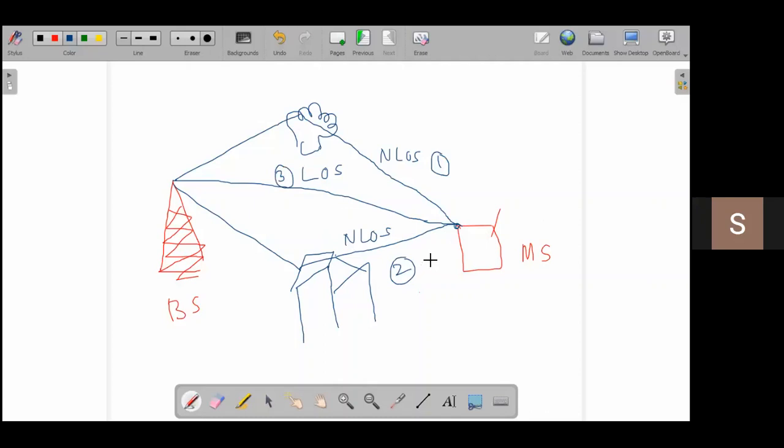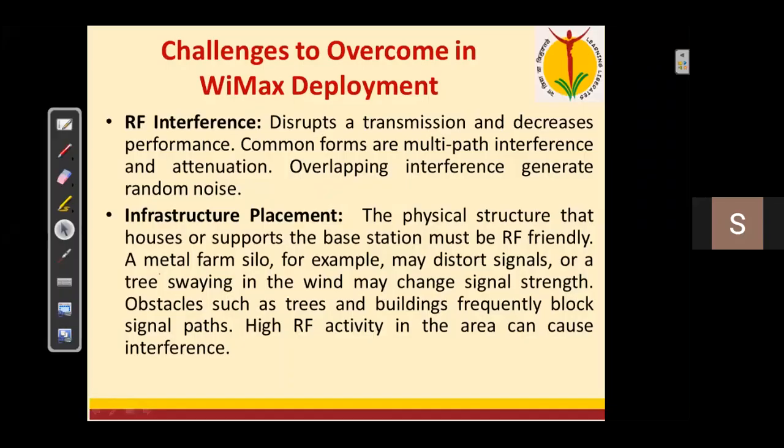You know that if there is a 180-degree phase shift, the signal becomes negative, and that negative signal and the positive signals add together, so it decreases the strength of the signal. Therefore, we have to survey the area where the signal comes from the base station to the mobile user, so that it adds constructively and avoids interference from the many objects in the vicinity of that base station.